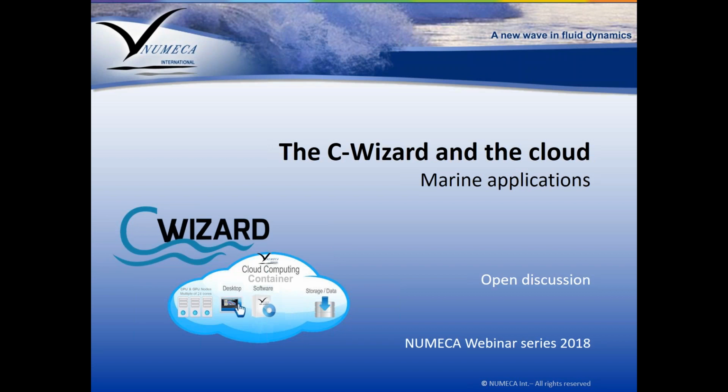Yes, this is extremely difficult. If someone has a magic rule, I would be very happy for that. But sadly, for the moment, I don't think it exists, because this cost estimation, or the CPU hour estimation, always depends on the geometry. What I can provide is, for instance, whether you have a bare hull, or appendages such as a shaft or a rudder, or bilge keels, or whatever particular structure. You can tell me, and for me it will mean something.